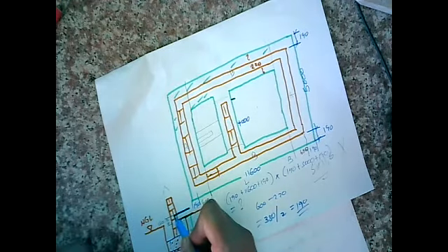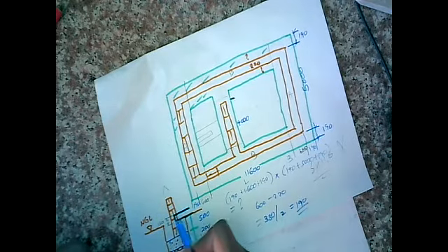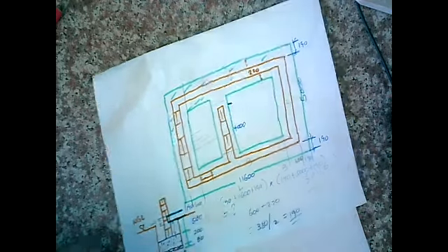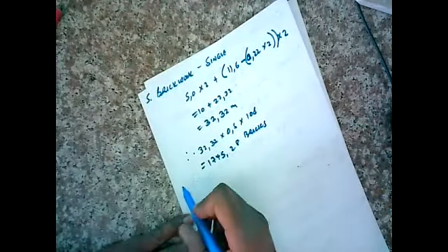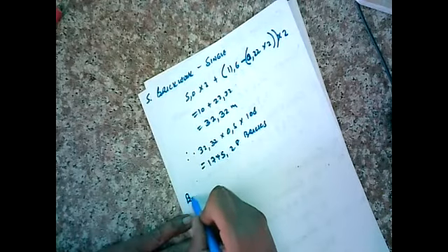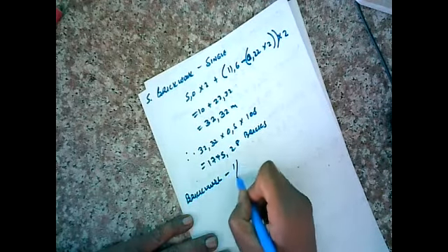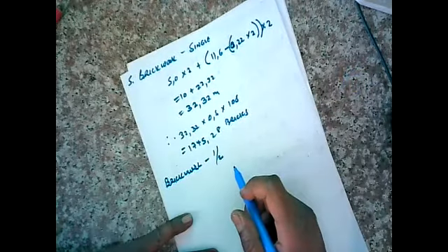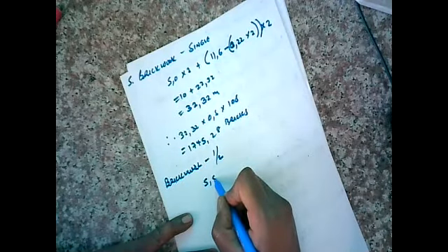What happened here though? It's not a single brick wall, it's a half brick wall. Can you see? The slab sits within that, basically resting on it. So let's do this one. Let's say brickwork half. Right. Now, where did I get this number here from? 5.56.